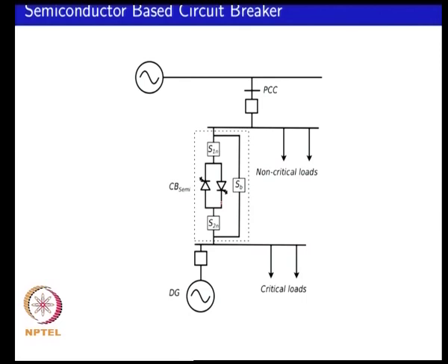So, there are a variety of approaches such as this that are available, but again you have the issue of handling the power required, the peak power, which would then reflect back in terms of the junction power loss, and also the increased cost of now having just a simple breaker being replaced by a more complicated system consisting of semiconductors plus the other switches for normal operation and different modes of operation.